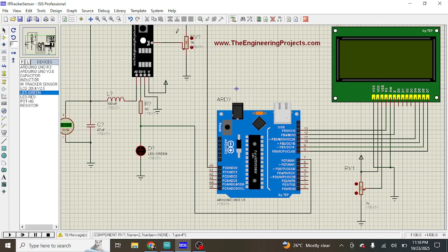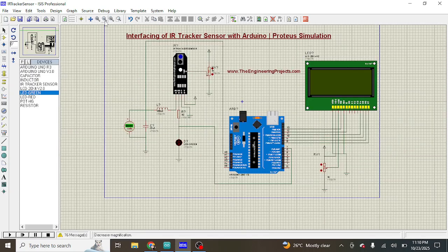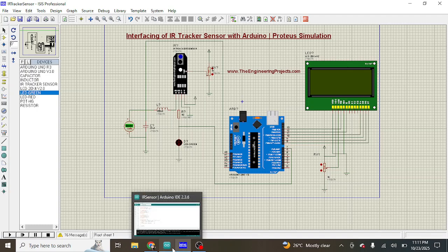As you can see, the potentiometer is connected to the test pin. So by varying the resistance of this potentiometer, you are varying the values on the analog and the digital pins. These values are then programmed through the Arduino. You can see that the analog pin is connected to the analog pin of the microcontroller and the digital output is connected to the digital pin of the microcontroller. So whenever the user changes the values here, the change in the voltage and the digital signals are fed into the microcontroller, which converts these changes into the IR readings, and these readings are then displayed here on the LCD.